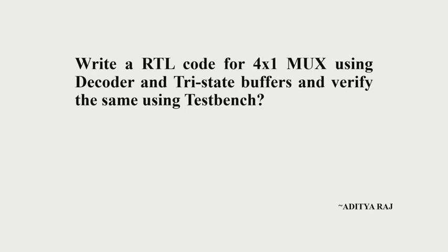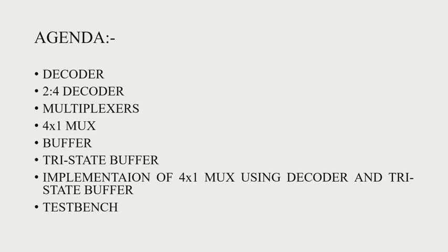Hello everyone, my name is Aditraj and in this video I'm going to talk about how to implement a 4:1 multiplexer using decoder and tri-state buffer. Later on we will also discuss the Verilog code for the implementation of a 4:1 MUX using decoder and tri-state buffers.